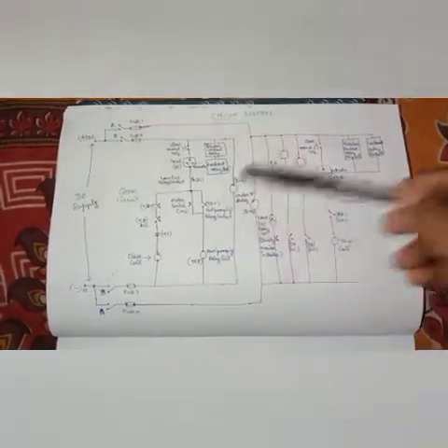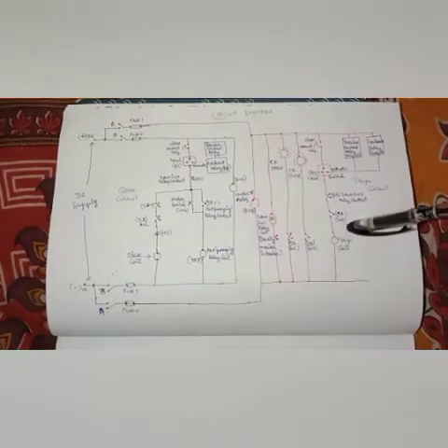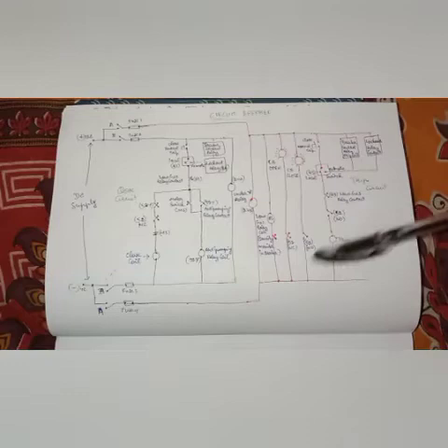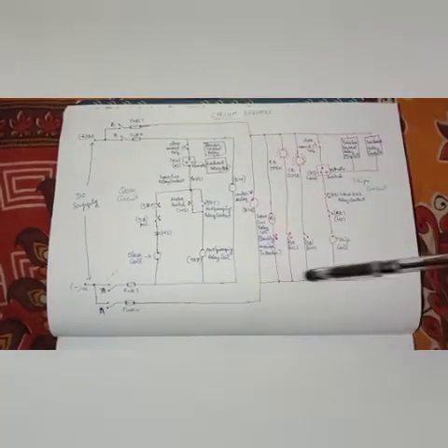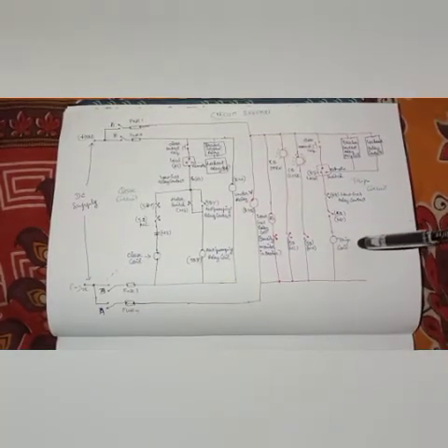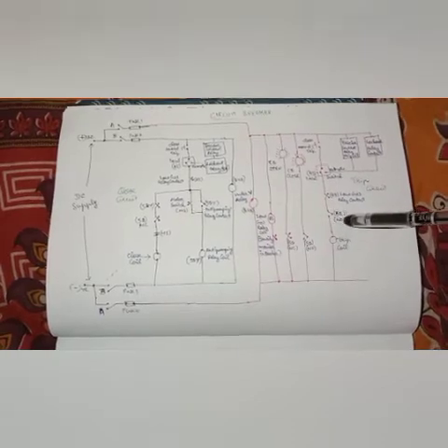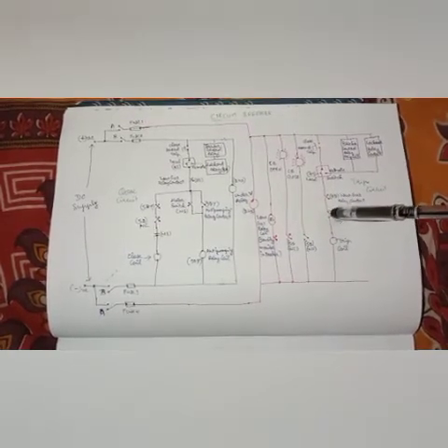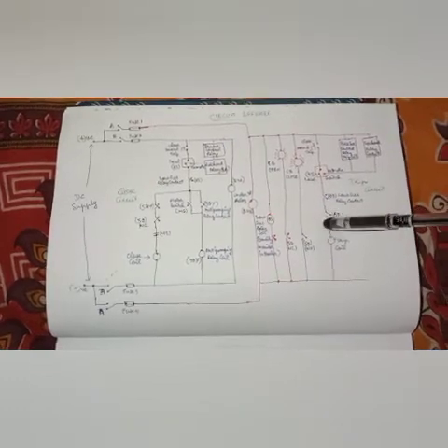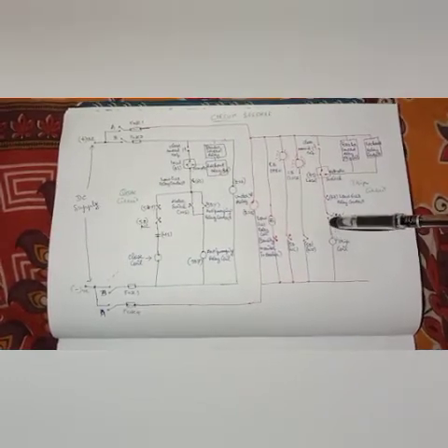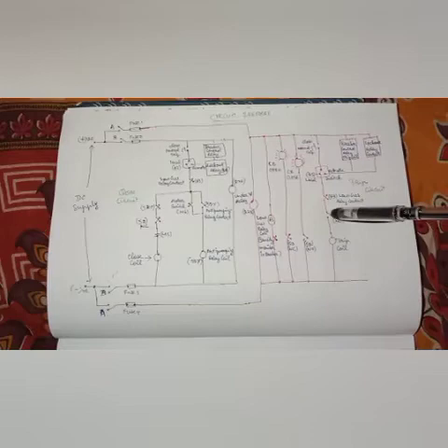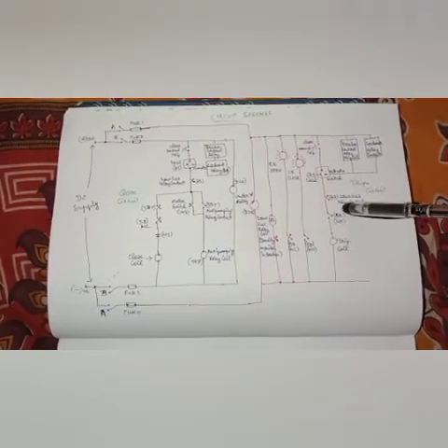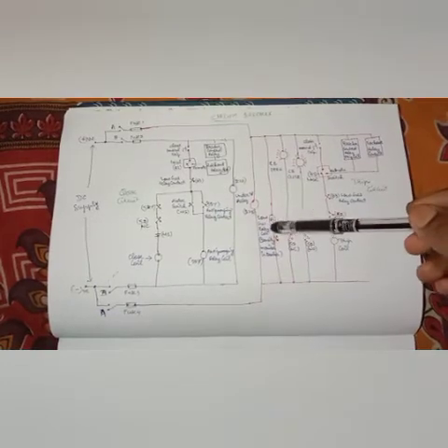And then the tripping, we are going to give the tripping initiation. For that we are going to check the negative supply, and the negative supply will first go to your tripping coil, and then check the NO contacts. Now the breaker is in close, so it will further change into an NC, which means the negative supply will further move to your low gas relay. Now the gas is in perfect condition, so this coil is in drop.